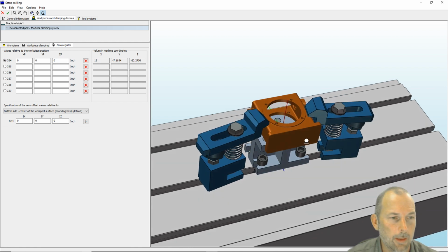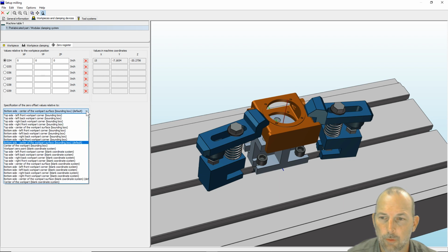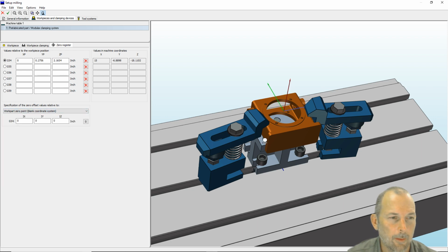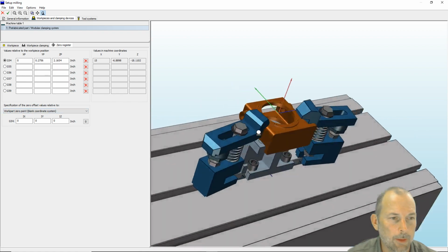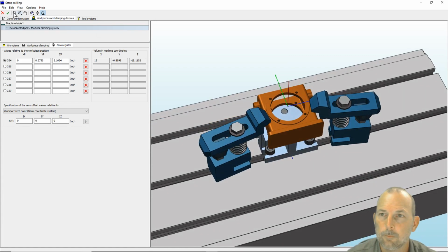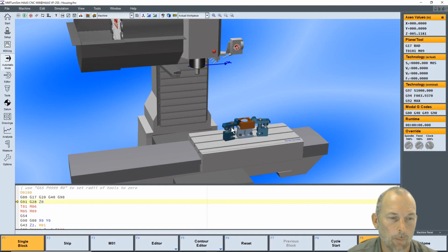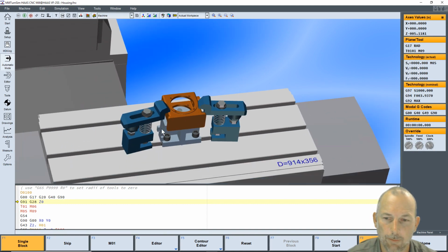And remember I said it'll make our life a little bit easier to save this STL about coordinate system number 1. I'm going to just choose from my drop down work part 0 point. That puts my G54 location. I use G54 on this program. My G54 location right at the top center circle. Pretty happy with that. So now I've got a little more realistic clamping situation.